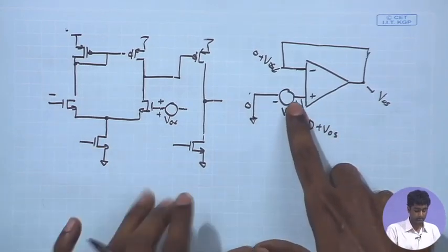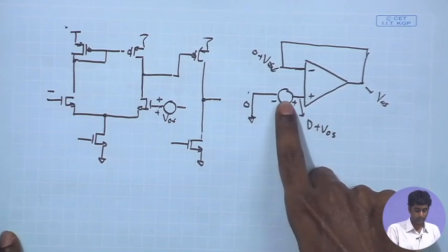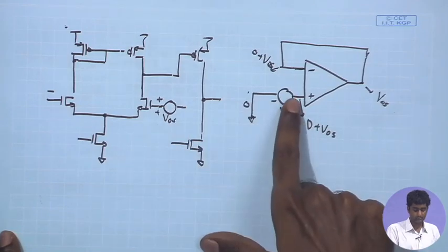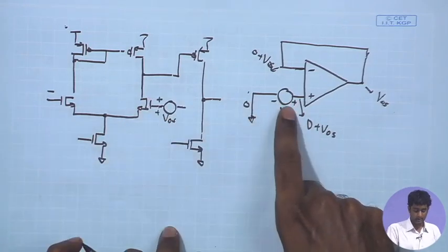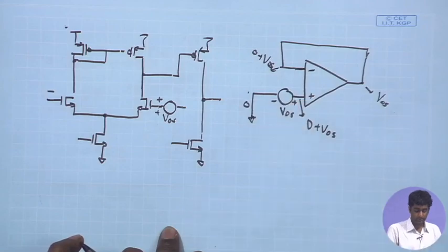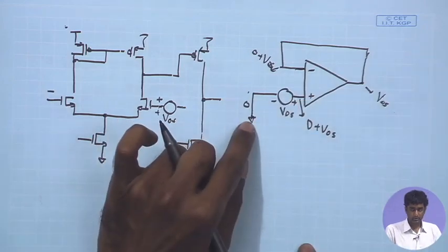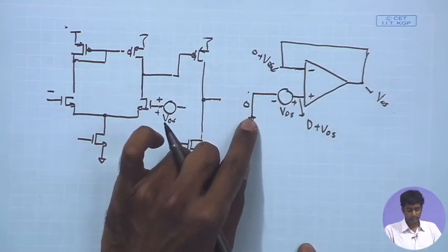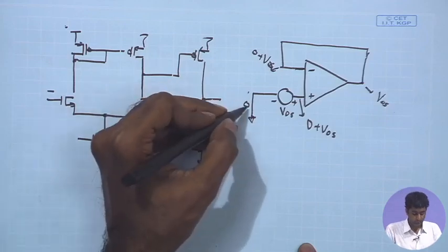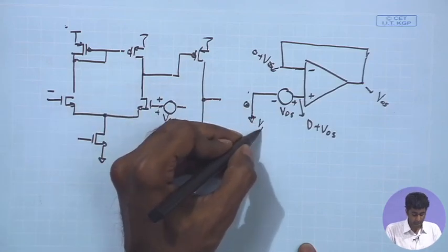So, as I said, here if you have an amplifier with an offset, rather than having a perfectly matched pair, and then rather than putting a DC voltage of an absolute 0, suppose I have a DC bias point which is say VDD by 2.